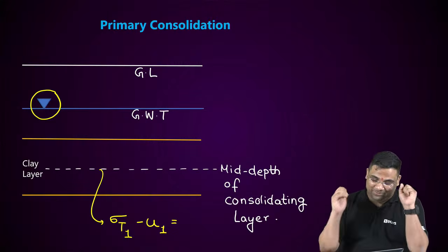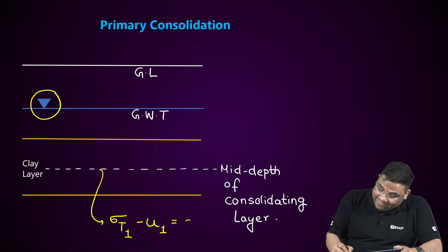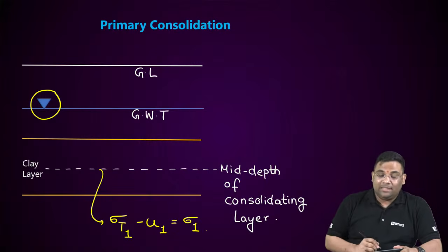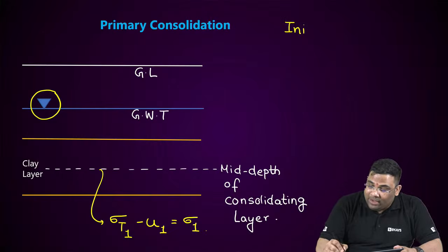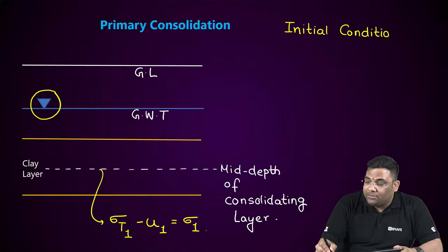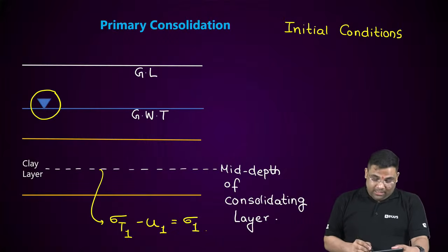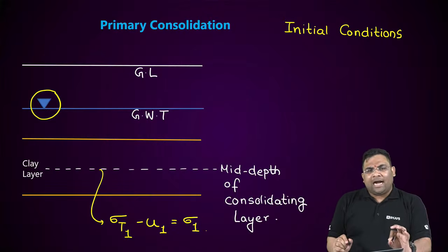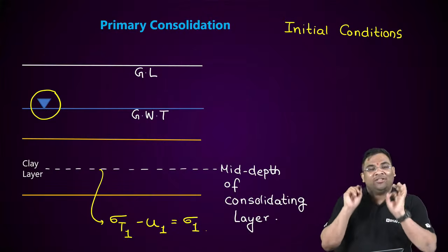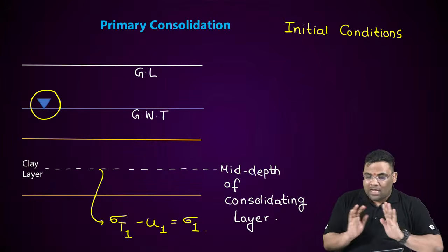Yes, yes, that is effective stress. So I'll get the initial effective stress. So these are the initial conditions. Now why am I calling them initial conditions? Because the consolidation has not started. When will the consolidation start? It will start when the additional stress comes into the picture, right? So now it has not started.